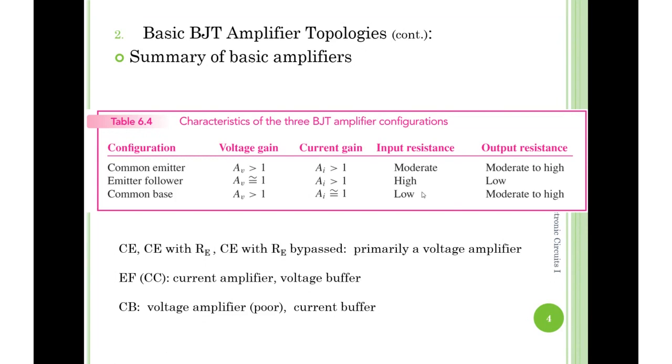Input impedance is like what? Voltage divider. Output resistance or impedance, also following a voltage divider principle. The input resistance of the amplifier determines how much voltage you actually can have occupied out of the input source. So the higher the better, or the lower the better? Absolutely, the higher the better.